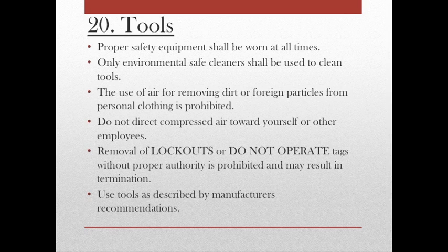Only environmentally safe cleaners shall be used to clean tools. The use of air for removing dirt or foreign particles from personal clothing is prohibited. Do not direct compressed air toward yourself or other employees. Removal of lockouts or do not operate tags without proper authority is prohibited and may result in termination. Use tools as described by manufacturer's recommendations.